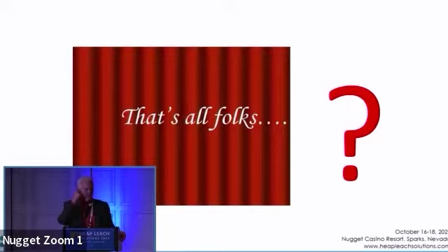I mentioned before that there was talk yesterday about 100 times being the goal, 10 times maybe. If you're at 10 times the permeability, then I would say you're done with screening. It's not going to liquefy. If you're less than 10, but above 3, now you kind of have to do that hard work. If you're below 3, it's vulnerable to liquefaction.